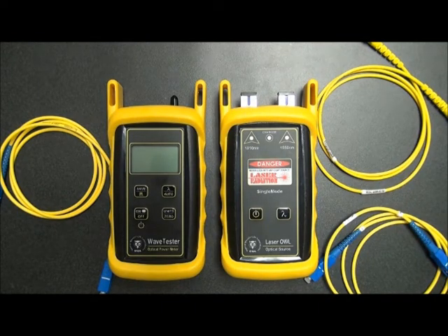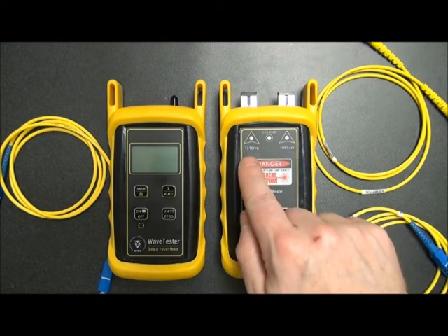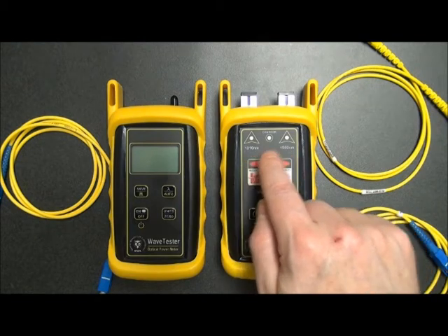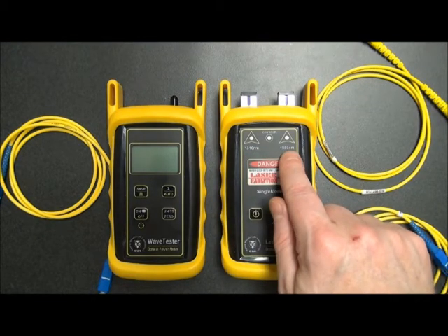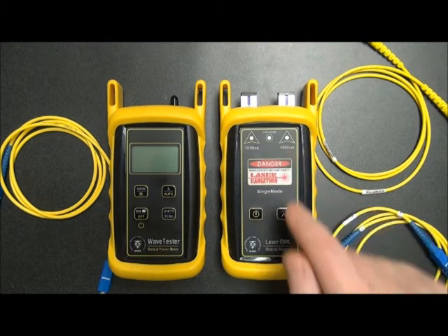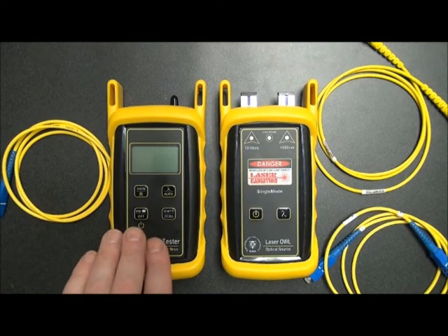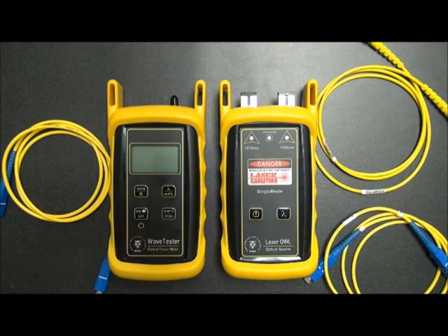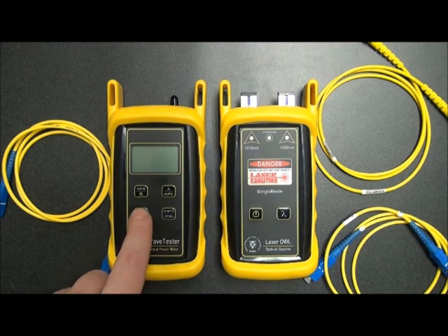Well, what I'm demonstrating here today is how to do a dual wavelength measurement, so testing at both 1310 and 1550. Because there are 2 ports here, one for each wavelength, we will need a reference cable for each port. The 3rd patch cable will stay with the WaveTester on its side of the test. So, in order to check these patch cables, we simply press the power button on both units.